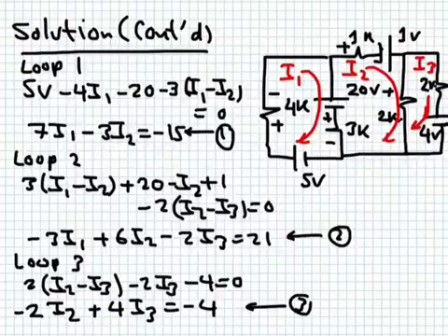I have three unknowns, I1, I2, and I3, so I have to get three equations. We go around this last loop, which is a small loop, and again I'm going to keep the same polarity here, positive, negative. This assumes that I2 is getting I3. I3 is flowing in this branch, then the drop across this 2 kilo ohm is positive at the top terminal, negative at the lower terminal. So let's go around this loop and apply KVL.